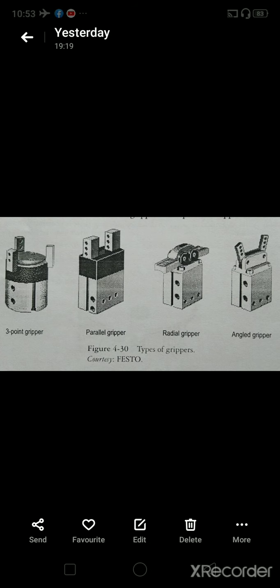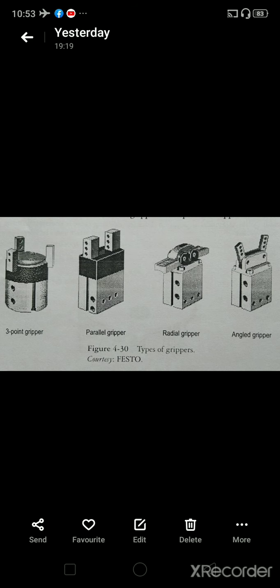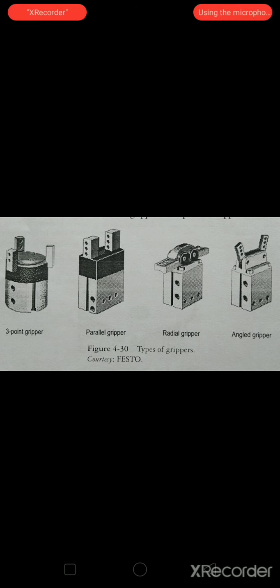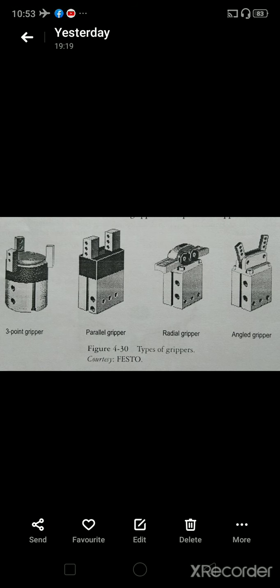The major technological parameters are the time available for gripping, the gripping force, and the number of workpieces to be gripped simultaneously. The most important workpiece parameters are mass, shape, surface property, material, strength, and temperature. And the most important environment parameters we should look after are process forces, space available for gripping, dirt, humidity, and vibration.